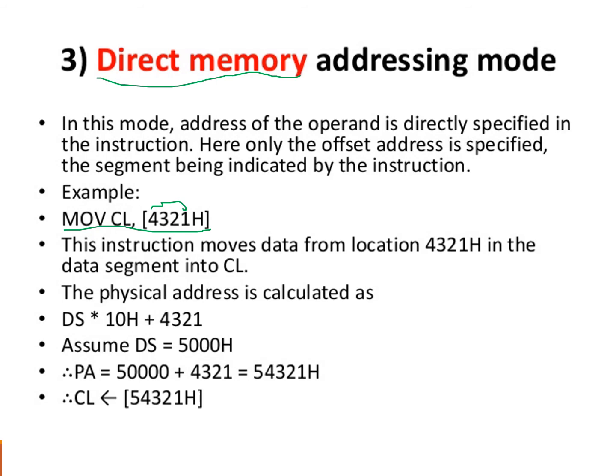It is the offset address. While discussing the architecture of 8086, I clearly mentioned that this offset address is added to the base address, which is the segment register multiplied by 10, which in turn generates the physical address, the memory location. That physical address is one of the memory locations of the respective segment of 64K locations, right?